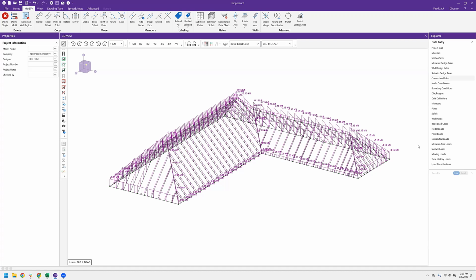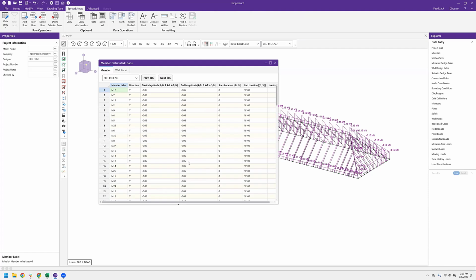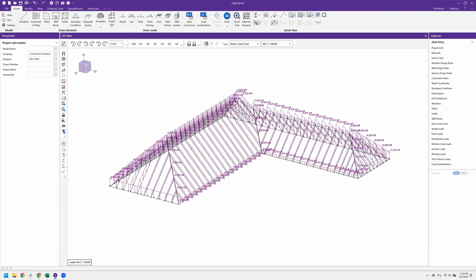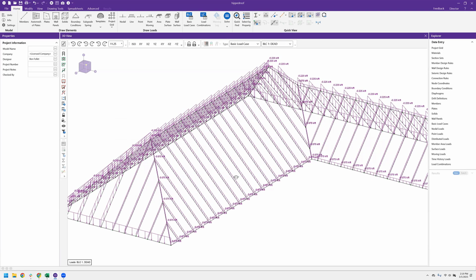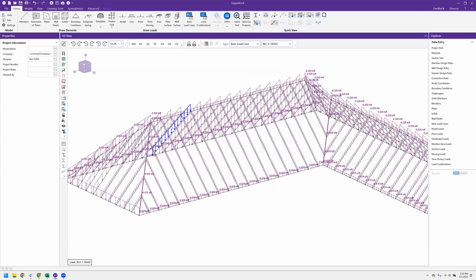And so very easily, I could go ahead and open my distributed loads spreadsheet. Instead of trying to grab these loads and change them manually, I could just grab all the N magnitudes, both columns. I'm going to right click and say I want to math on selected cells. And instead of adding, I'm just going to multiply and increase all of these by a factor of 1.5. So now really quickly and easily, I could increase or decrease or add or divide or whatever the loads on the model across the board just by doing some math in the cells, in the Excel spreadsheet sort of deal.